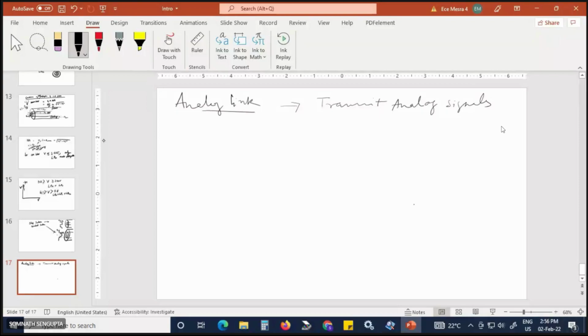So here, say, if you use transistor and here one LED source we use, then it is plus VCC say, and this is LED. So if this is your input signal, if you apply sine wave, the current will vary accordingly through the transistor and intensity of the light will change.